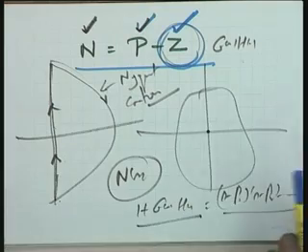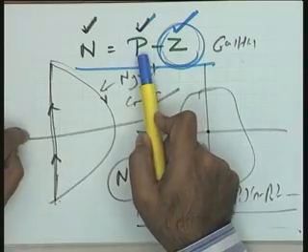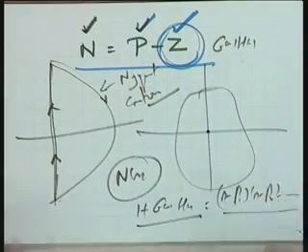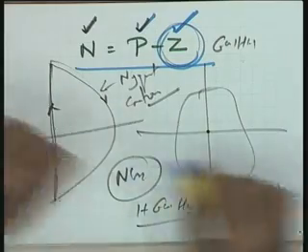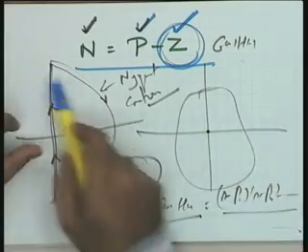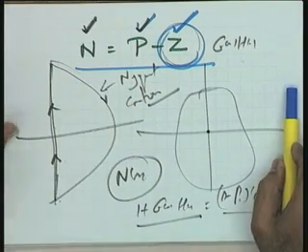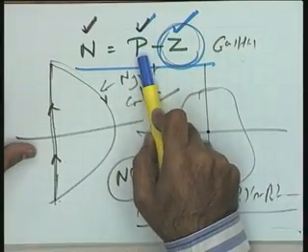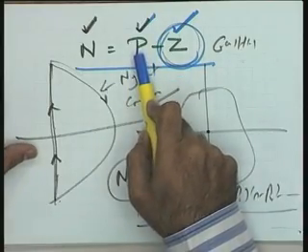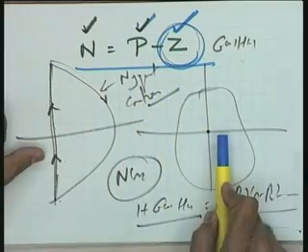That is why I repeated this statement, an open loop stable system means capital P is equal to 0. Note this point please. 90% of cases will be of this nature. That is why I am making this. This Nyquist stability criterion should be clear. Most often we will come across this statement that for an open loop stable system P is equal to 0. So if you have a case for which P is equal to 0, in that particular case, the system is stable.